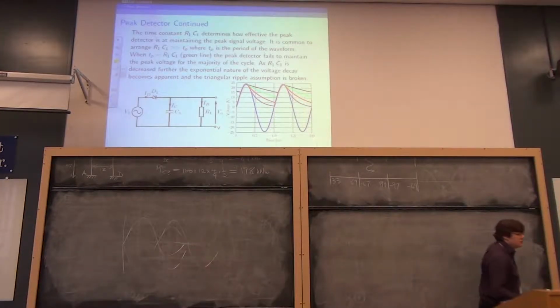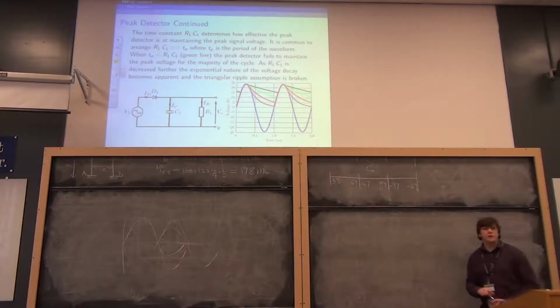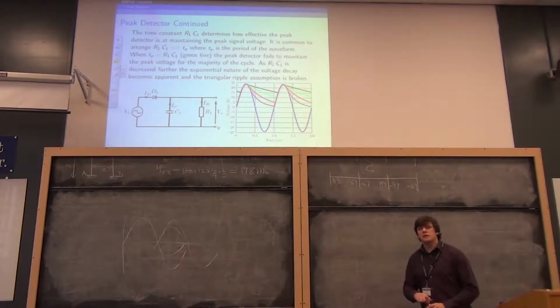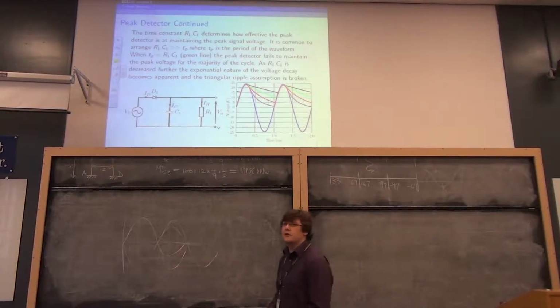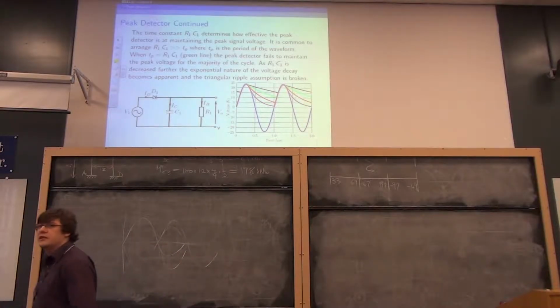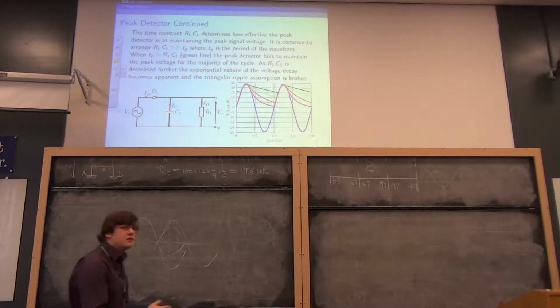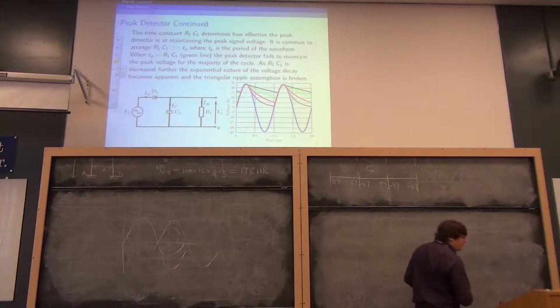So, carrying on, there is a time constant, R1 and C1. That's to say, if you did C1 in farads times R1 in ohms, you get a number whose units is seconds. And if you're not keen on the idea of that, if you go on Wikipedia what farads is in base units and what ohms is in base units and do all the crossing out, you'll end up with kilograms over something times seconds over kilograms times something times seconds. Anyway, you'll end up with seconds. So there is a time constant, which is R times C. RL will give you a time constant as well.